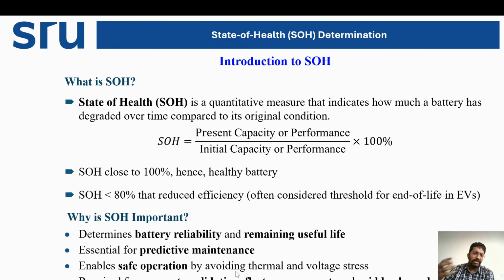So these are all higher end applications where multiple vehicles are being used. Which battery will be put in which vehicle, so fleet management is there. Then grid level backup planning, so how much the battery bank will be able to supply for the duration. So what is the capacity, hours of backup required. What is the percentage of critical load involved. Warranty validation, how much is the warranty period. So all these things come under the state of health.